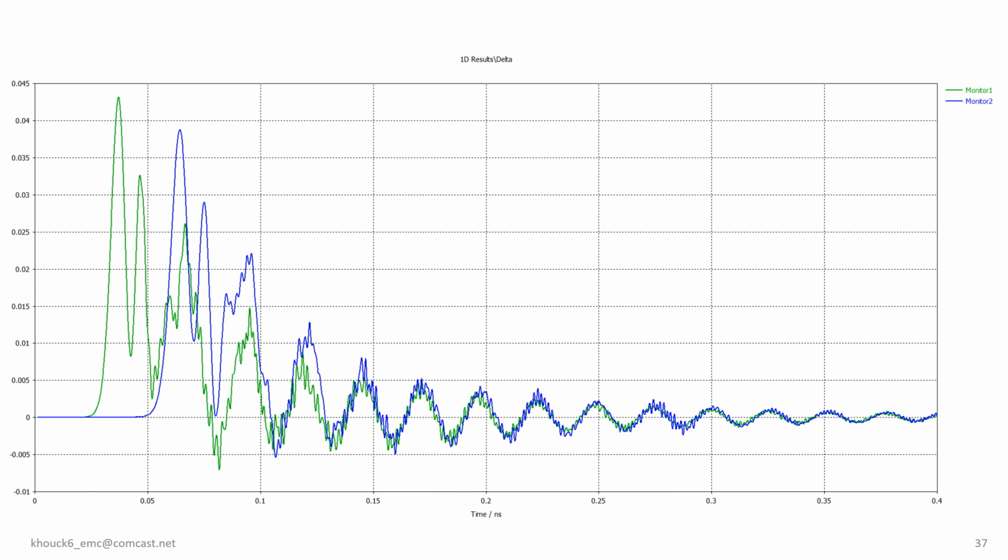When examining the deflection or change in slope along a trace from its source to a specific point, it becomes evident that only a fraction of the electromagnetic E field propagates down the trace. Despite the signal's initiation at the source, its journey along the trace is subject to various factors such as reference transitions, substrate properties, and trace geometry. Consequently, the distribution of the E field along the trace is non-uniform, with only a limited portion of the initial signal's energy effectively traveling down the trace.